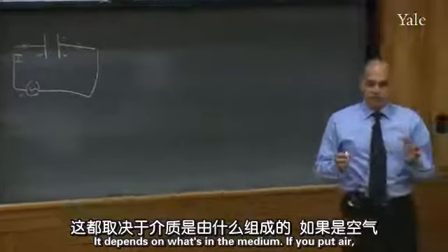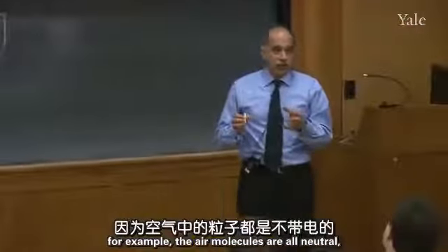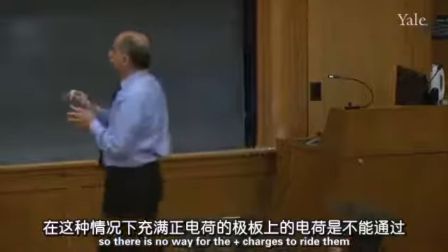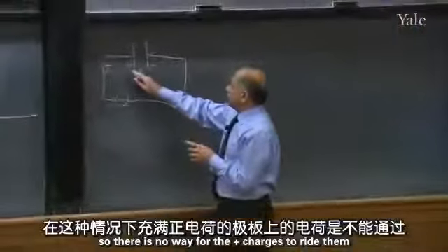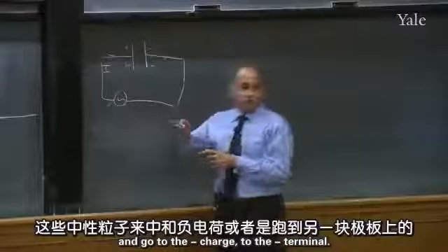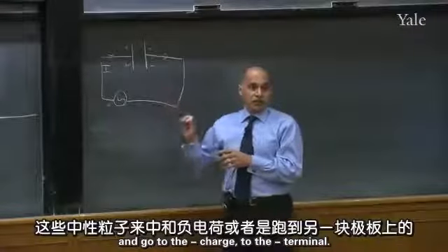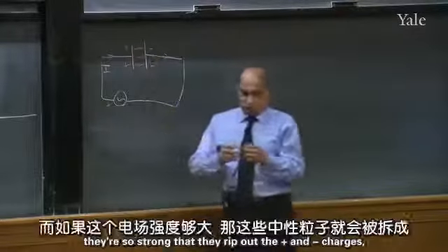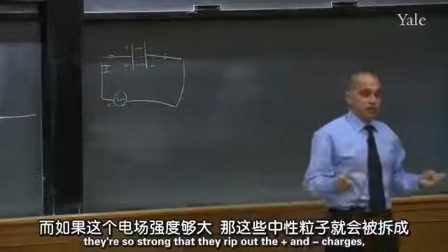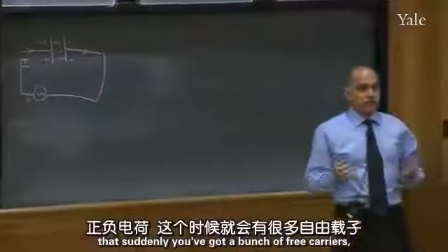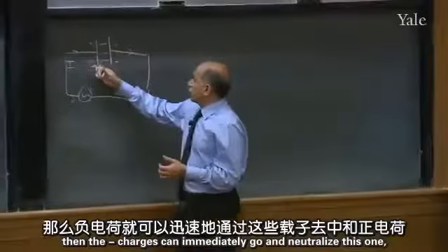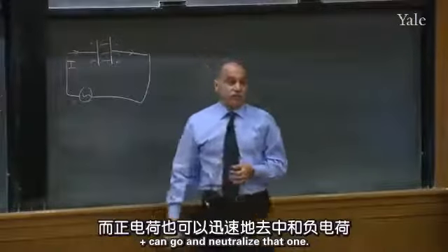If you put air, for example, the air molecules are all neutral, so there is no way for the plus charges to ride them and go to the minus terminal. But if the electric fields, and this will certainly produce electric field, are so strong that you rip out the plus and minus charges, then suddenly you've got a bunch of free carriers. Then the minus charges can immediately go and neutralize this one, and plus can go and neutralize that one.